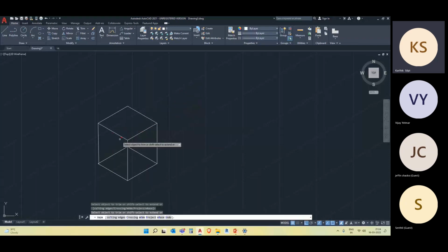If you are looking from this angle, why should we remove this line? Because it is in the bottom of the cube. If you are placing a cube on a surface, you cannot see this bottom, right? That is why we have to remove this bottom part. One more thing we have to remove is this part. So when we view something in these directions, only these planes will be visible. The part that is present in this corner is not visible in this particular isometric view.